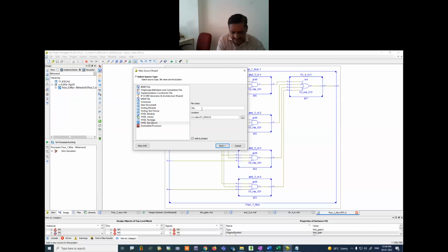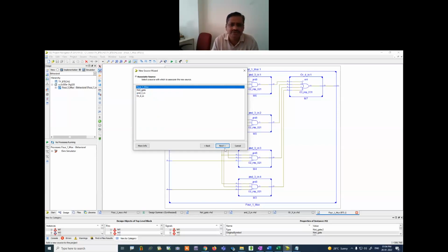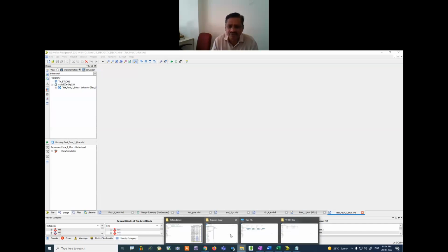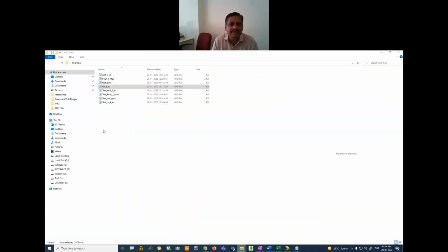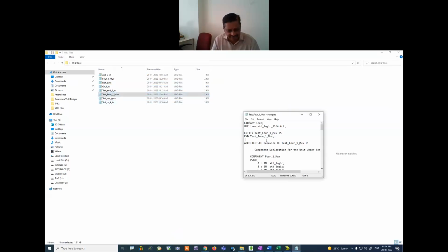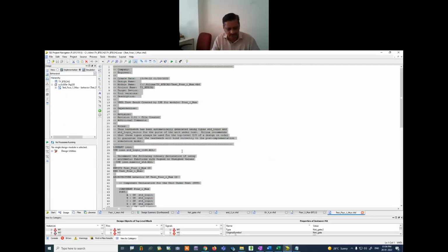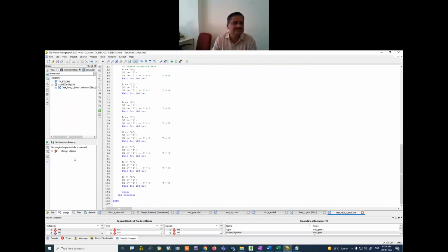I can just give the name test underscore 4 underscore 1 underscore mux, and here I click Next. I have to do the 4:1 mux, Next and Finish. I don't do anything else. The test file that I created earlier, the test file we had written, I am copying that test file here, 4:1 mux test, 4:1 mux. I do Control A, Control C, just I will do that. I will come to this, I will Control A, I will paste here, I will save this design.